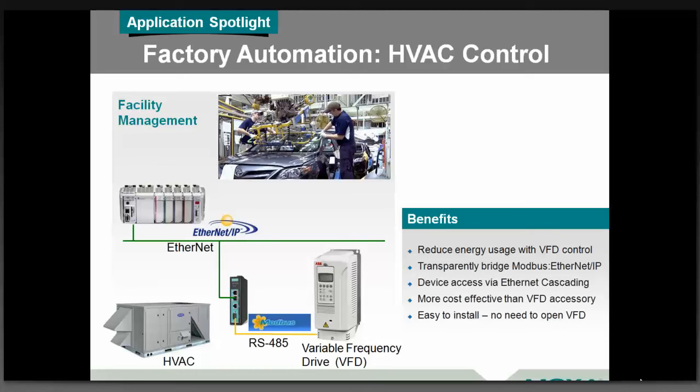In this case, we're utilizing a gateway that's able to talk Modbus, which almost all of the VFDs on the market right now, even the smallest, most inexpensive ones, have as a Modbus serial interface. And if you utilize a gateway, you can get that onto Ethernet. And in this case, even convert between vendor protocols, going from Modbus serial on the drive to EtherNet/IP on Ethernet.